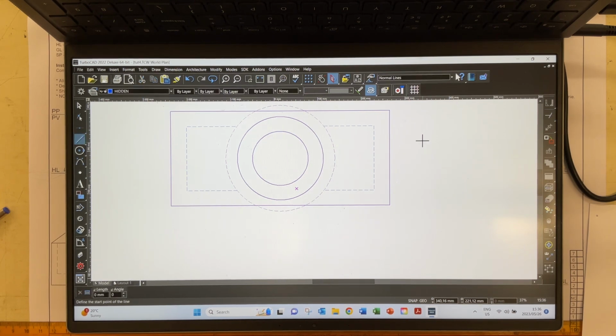Okay, press escape. Now I need to remove that part of the circle and that part of the circle over there, so I go in here, trim again, going to trim on that and that, enter, and I can now trim that part over there. Now that didn't work very well, did it? Because I've lost my little circle over there. So let's just do Control Z there.